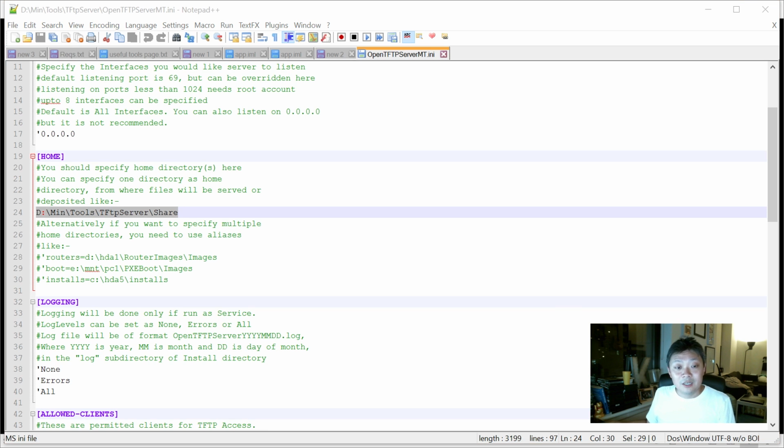Okay, great. So after OpenTFTP, we're going to start configuring the Yun. Okay, I've got a list of files that you're going to have to download. So the first thing that we're going to download is the generic Linino boot bin file. Okay, and I'll have that documented. So let's just hypothetically say that it was downloaded and put into that OpenTFTP share folder. I'm going to go ahead and confirm that it's in there for the sake of this demo.